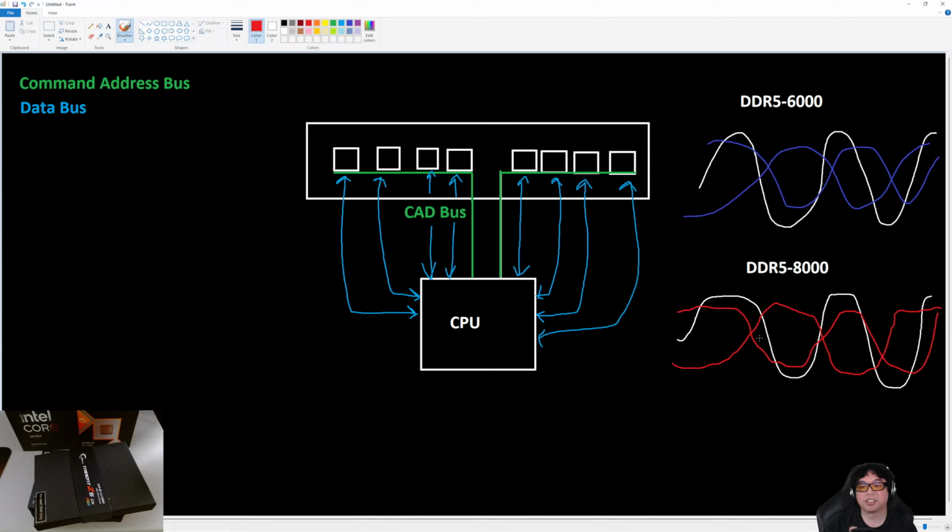You know what also affects the stability and the shape of this eye diagram? Temperature. The hotter the memory is running, the more noise and the more jitter is added to the system because of the thermal effects on the electronic device. When it is running at a higher temperature, you get more micro vibrations of the electrons, so they move in a more irregular pattern.